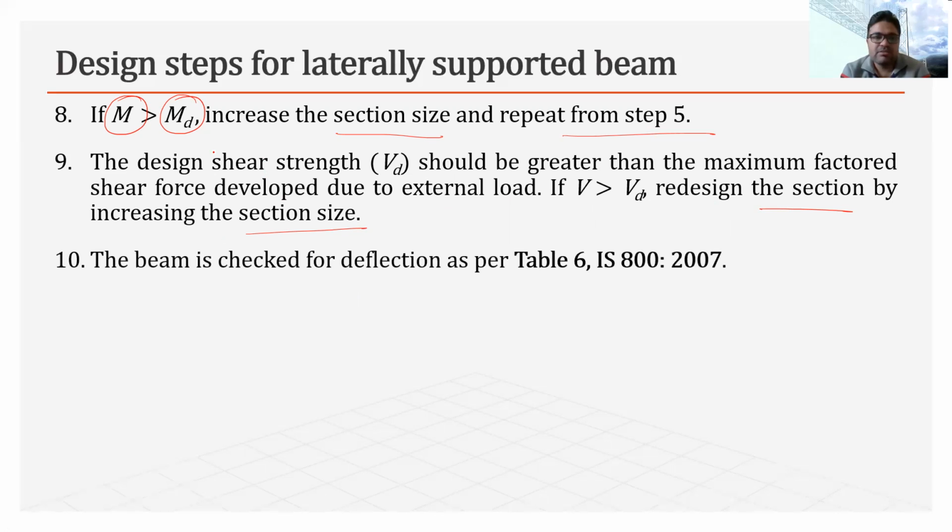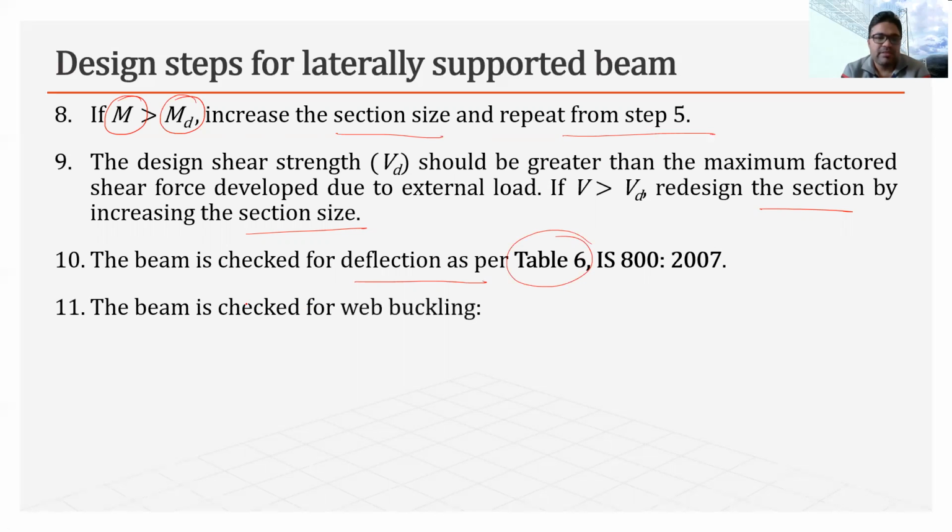Then once we are satisfied with steps 8 and 9, we will check our beam for the deflection criteria as per table 6. Then in the 11th step, we will check our beam for the web buckling criteria.